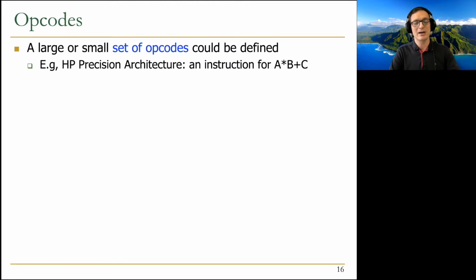And we actually want to add this instruction that can do multiply and accumulate inside our ISA. Now, that was actually a good idea, perhaps, if you think about machine learning today. Machine learning is full of matrix multiplication operations and accumulation, of course. Matrix multiplication requires both multiplication and addition operations. As a result, these multiply and accumulate instructions can come in very useful for workloads that demand them.